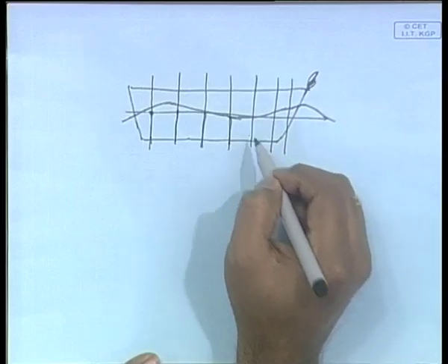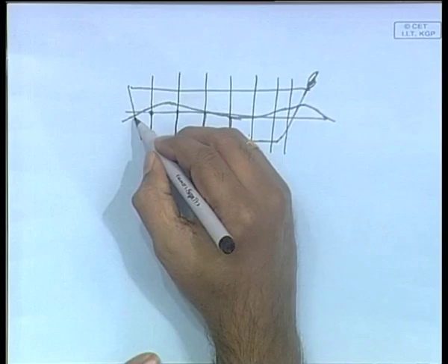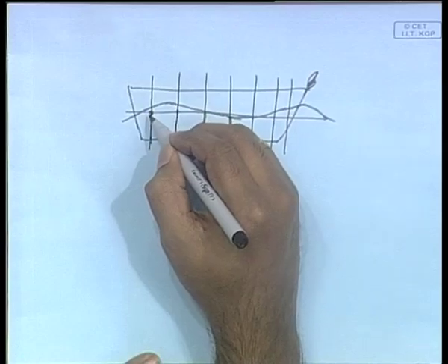So, it becomes very simple buoyancy curves. Buoyancy curves are all taken at the same draft, or of course, even in case of an even keel, there can be a slightly modified case when it is in a trimmed condition. In a trimmed condition, the drafts can vary with distance, but even then it varies in a very linear fashion. So, drafts vary in a linear fashion, and you get the different drafts. But in the case of a wave, as you can see, the draft varies probably in a trochoidal or a sinusoidal fashion, depending upon the type of wave.